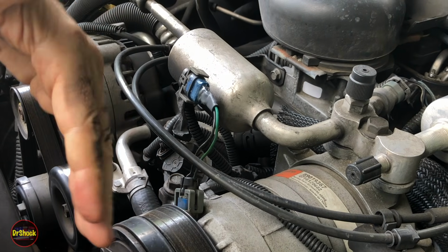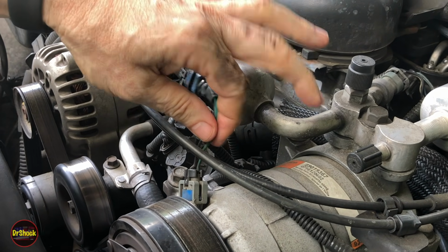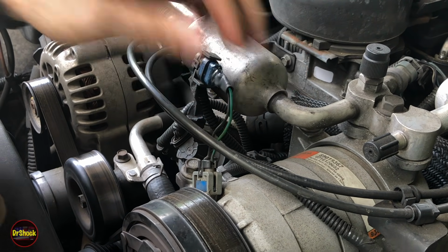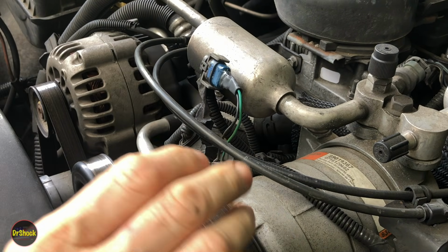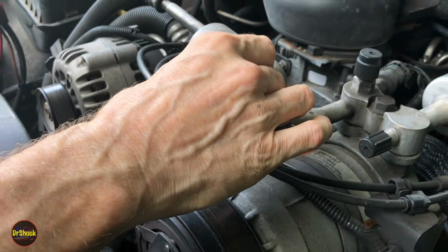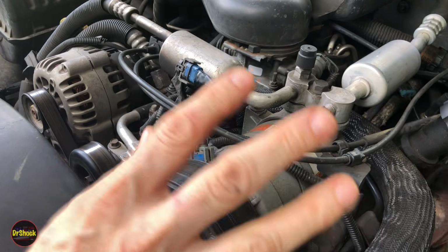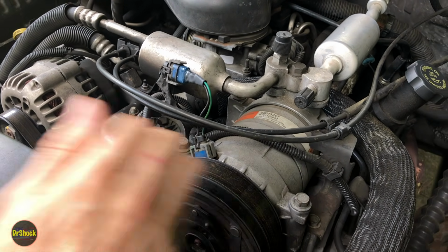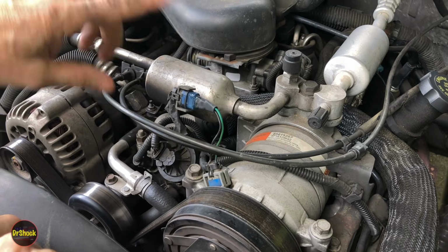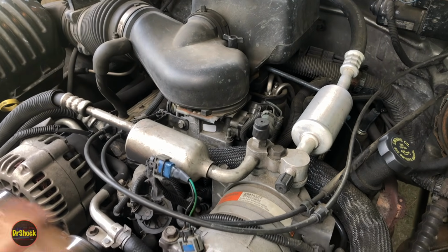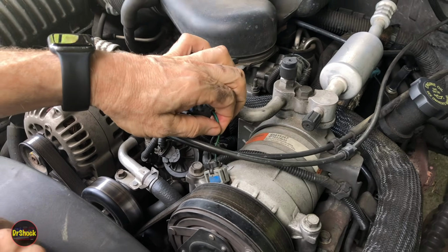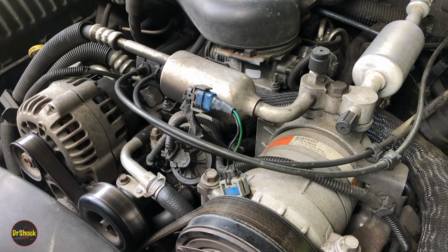If we get the compressor cutting out and there's no interruption of power, then we can isolate this problem to the clutch area. If we find that the power is being cut when the compressor goes off, then we can eliminate the clutch part of this, and we can focus on using the scan tool to determine which of these possible switches were involved, or even the relay. So let me go ahead and hook everything up. I'll show you what the hookup looks like, and then we'll go off for the test drive.